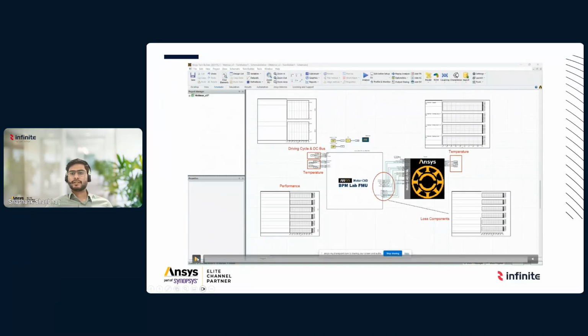For Ansys Motor-CAD integration, here we are using the drive cycle example previously mentioned, and you can see we have two components: the lab model and the Motor-CAD thermal model. The thermal model on the right has inputs which are all the loss components that come from the Motor-CAD lab module.